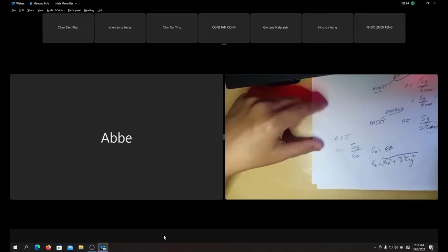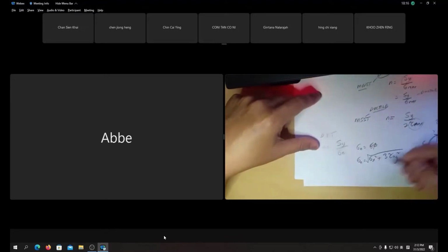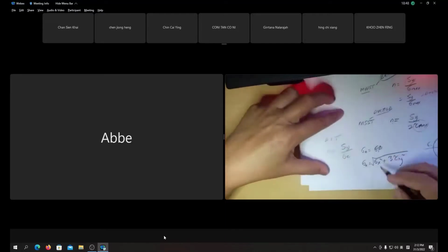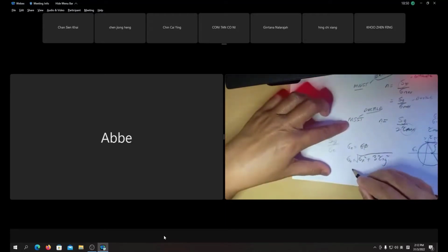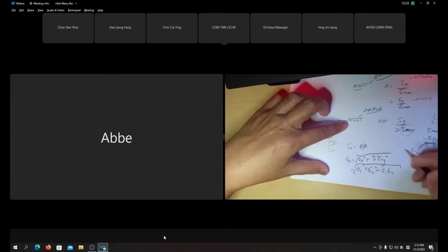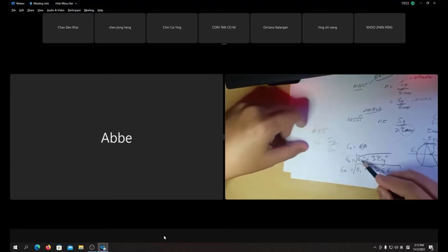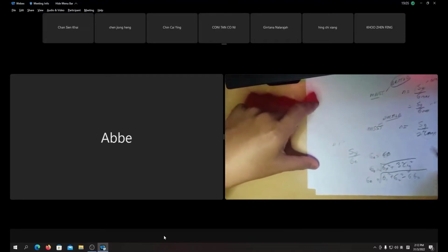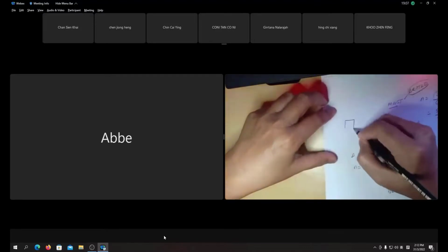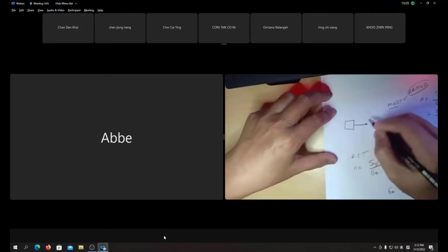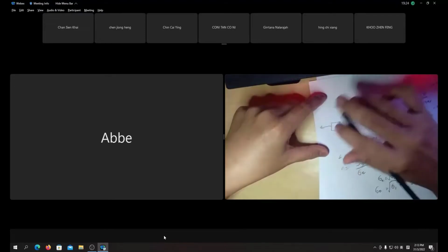If you happen to have biaxial stress, with sigma 1 and sigma 2, you can use the biaxial form directly: sigma equivalent equals the square root of sigma 1 squared plus sigma 2 squared minus sigma 1 sigma 2. Or sometimes, as a shortcut, you don't have to calculate sigma 1, just go directly by the axial stress. Most of the cases, for example our shaft, on our element. Can you hear me now?